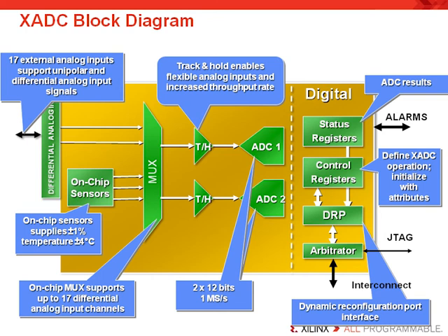Now, the ADC conversion data is stored in dedicated registers called the status registers. These registers are accessible via the FPGA interconnect using a 16-bit synchronous read and write port called the Dynamic Reconfiguration Port, or DRP. The DRP interface can run at extreme rates as high as 250 MHz, allowing designers to perform customization between the conversions if necessary.